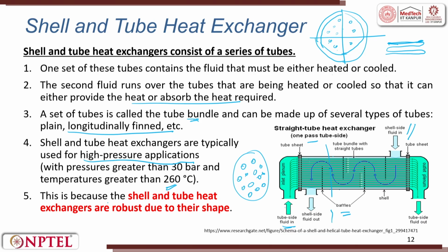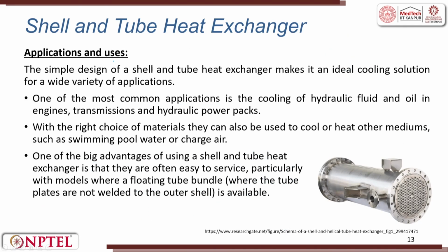This is because the shell and tube exchangers are robust due to their shape. So, 30 bar pressure inside a cylinder is not a big deal, and a 260 degrees Celsius operation is also not a big deal if using a steel material. So, the application of this, this is what I said, baffle. In the baffle you will see all the tubes which are attached. So, this can be in and this can be out.